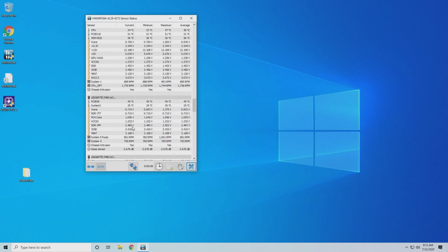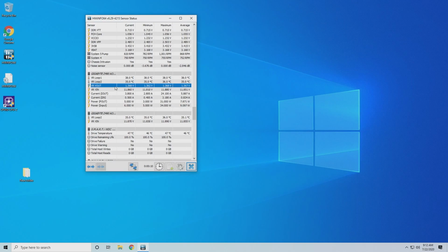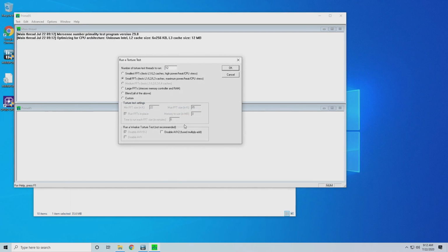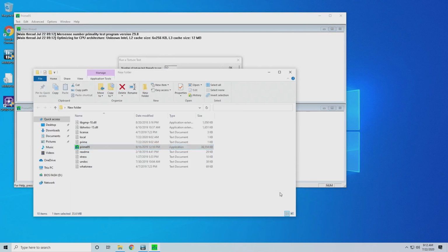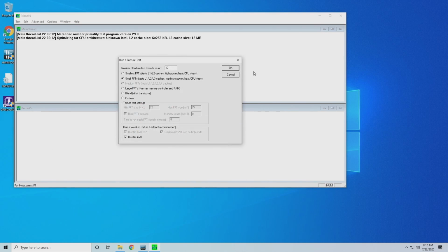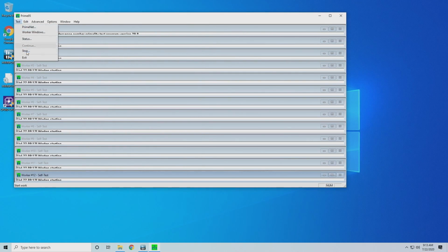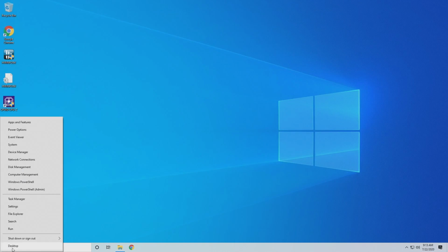Well, this is one fast PC. 1.368. Okay, so not too bad. Still very safe. 1.4 idle is a good thing to look for. 1.375 under load. Okay, let's see what we've got for load. We got 1.34 loaded. Okay. Alright, so we can go higher on the voltage.